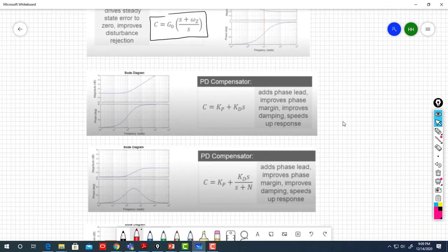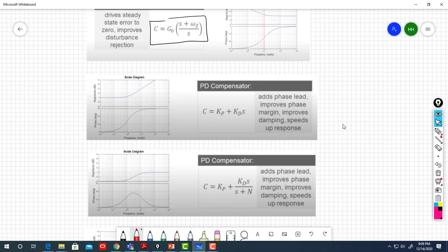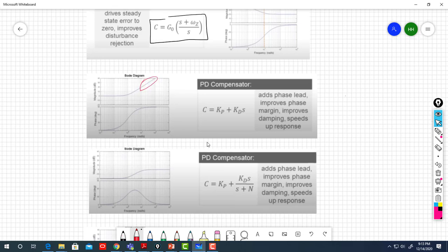Well, first here what they did actually, they add a filter to it. Numerically differentiating is not stable, differentiation is not stable, so it is better to add a filter, which is a low pass filter, so you'll cut off the noise of high frequency as well. So instead of being like this, you will be like this.